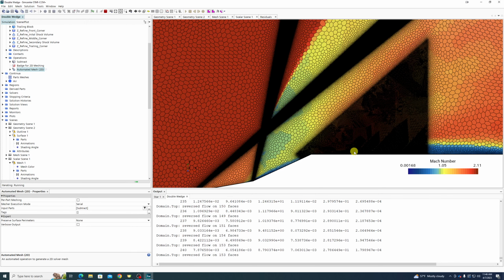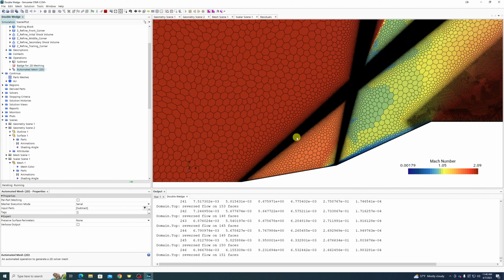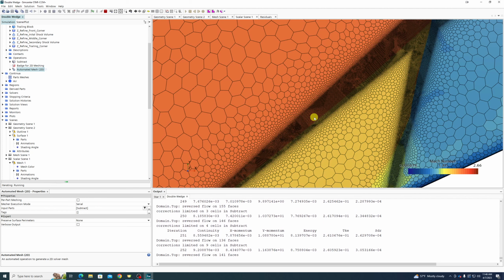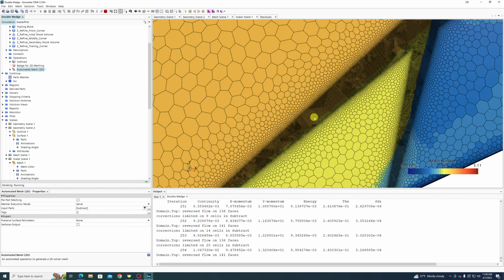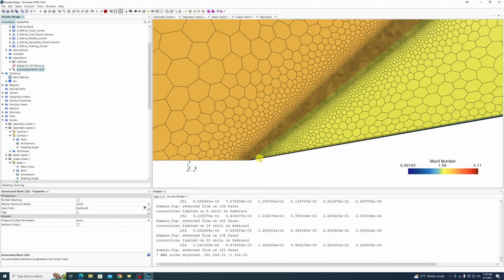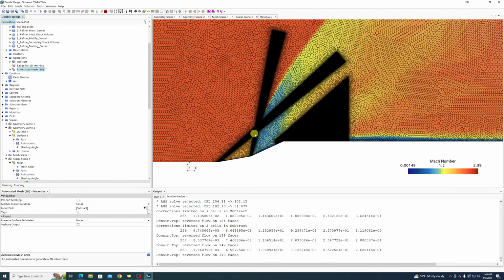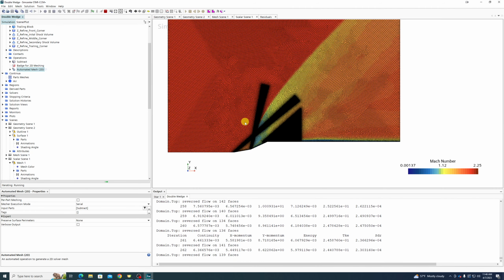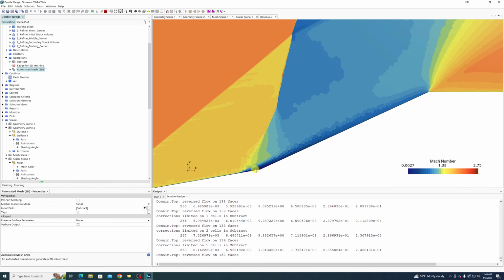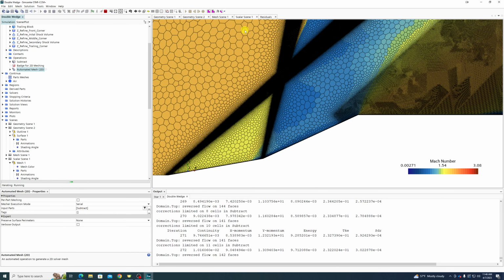But this is a basic supersonic simulation, and you can sanity check these shock angles. As a matter of fact, we did base this initial shock angle off of a theta-beta-Mach diagram, and it was pretty darn close. We were off by maybe a couple degrees, but that could be eyeball reading of a graph for starters. So that was pretty spot on. And there are some other changes we can make, but by and large, these differences are due to the fact that we have shock-shock interactions and other weird effects going on here.